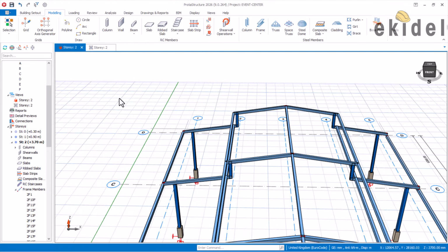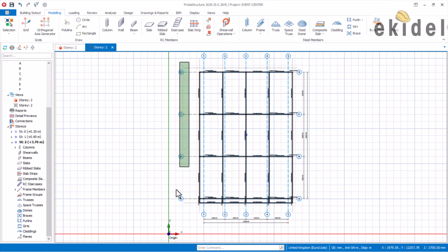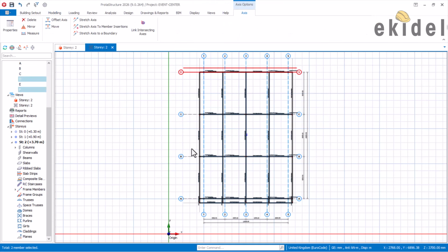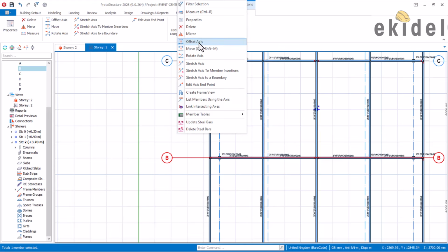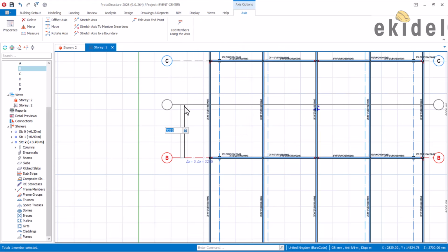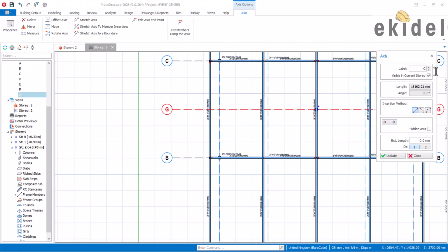To mirror that now, we need to find the center of these panels here. So we'll have this 6 meters, 6 meters. We are going to offset 3 meters from here upward, 3 meters here, 3 meters. That's the center of it. Now change this to hidden because this is not a major axis. Come here first, center line, and then hidden. Then keep this here and then update.